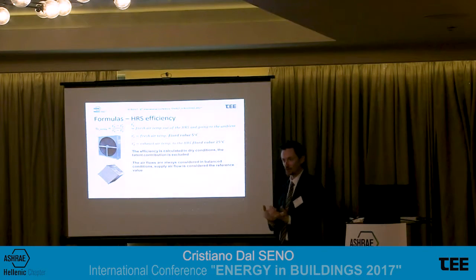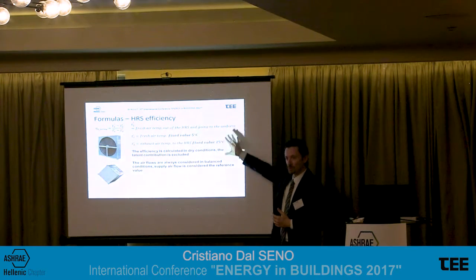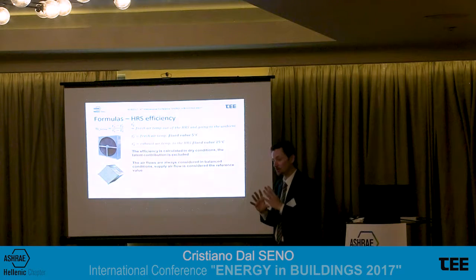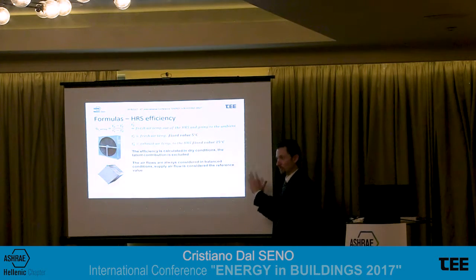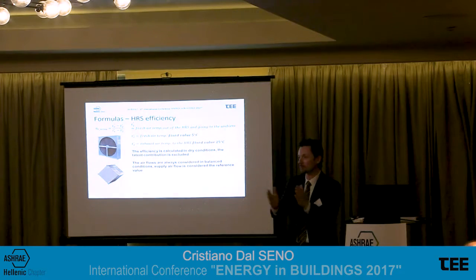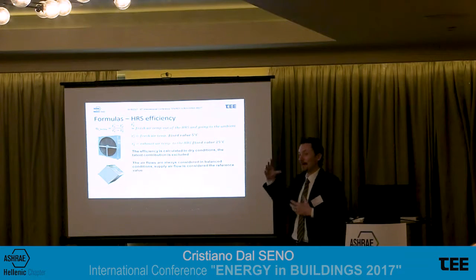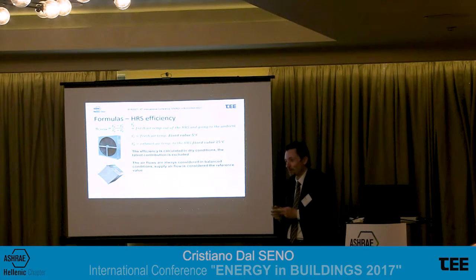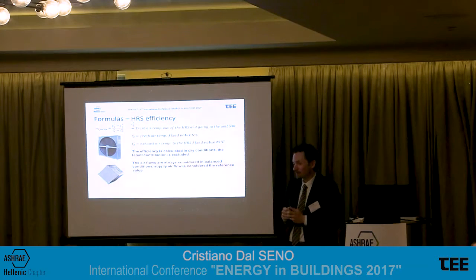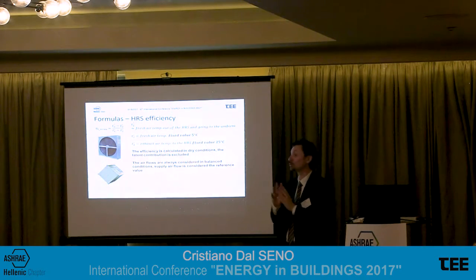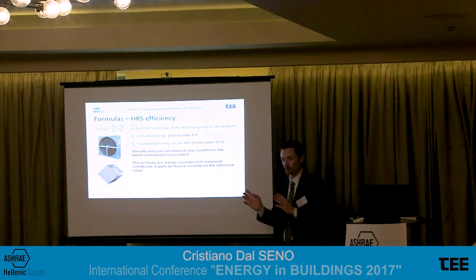Why 2 different values? One is at fixed conditions for the eco design. If we comply with 73% minimum, that is a plate heat exchanger that we can use in our air handling unit. Then, knowing that we can use it for the eco design, we calculate it according to the requirements given by the consultants. But nobody is allowed anymore to play tricks on the parameters, increase a bit the supply flow, or change a bit the temperatures in order to show to the people the efficiency you want.